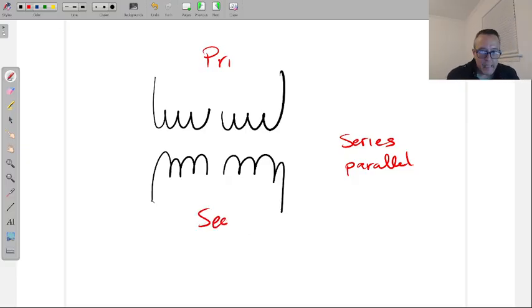And what ultimately this is going to result in is in us using the turn ratio of the transformer to our advantage. Because as we connect the primary side in parallel and in series, we're actually choosing between the different turn ratios that these transformers have available.